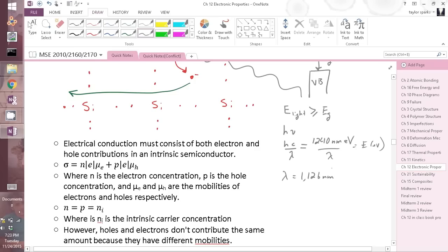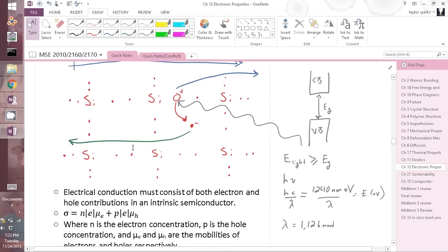Okay. Now, electrical conduction can arise in these semiconductors due to both the motion of the electron traveling to the left as well as the hole traveling to the right. How does the hole travel? A good way to think of that, I think, is just to picture what's happening. As this electron is able to hop and fill that gap, now this becomes the hole, and so forth. And so then this next one over could fill that spot, moving the hole here. So hole motion.